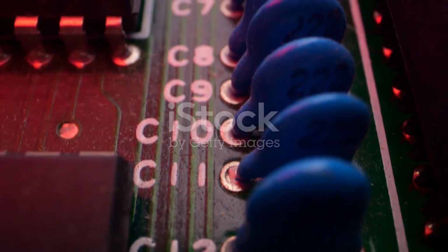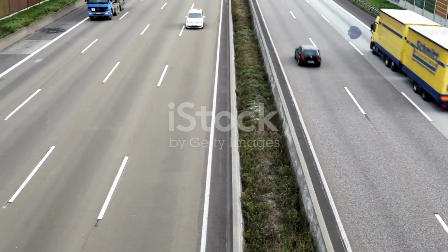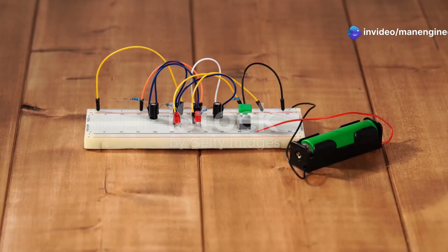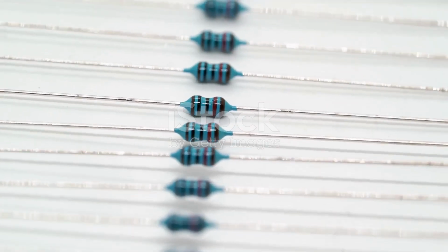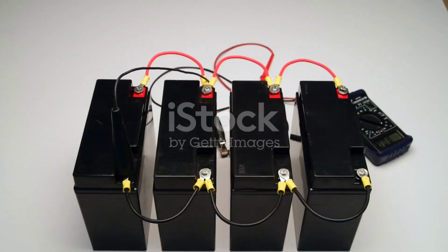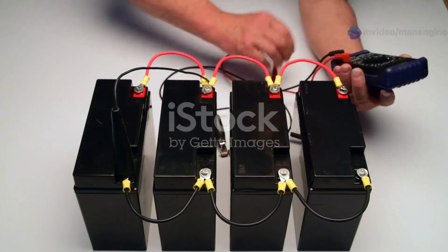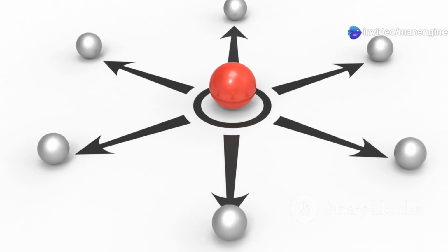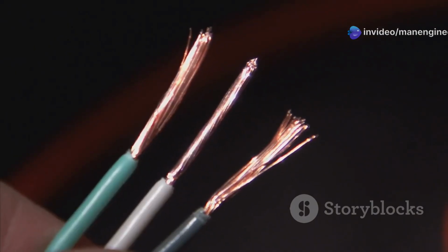Another way to connect resistors is in parallel. Picture several lanes on a highway, all starting at one point and ending at another. That's analogous to resistors in parallel. When resistors are connected in parallel, their terminals are connected to the same 2 points, nodes. This means that the voltage across each parallel resistor is identical. The total current flowing from the source will split. It divides itself among the available parallel paths.